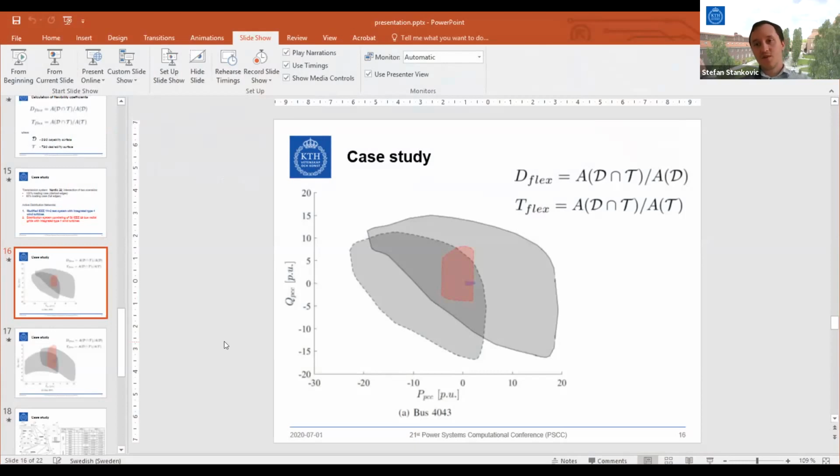Even if we were stuck in a local optimum somewhere and it is not a global optimum, it didn't cause any issues. The states of the system indicated that we were at a good operating point in the maximization. We cannot enter into the discussion about non-convex multi-optima. That's another problem. The point of this paper is to introduce this method of finding the flexibility coefficients, but any optimization problem for finding the DSO capability surface or TSO desirability surface can be reformulated, for example as a linear optimization problem or a convexified formulation, which was not really the main topic of this paper.